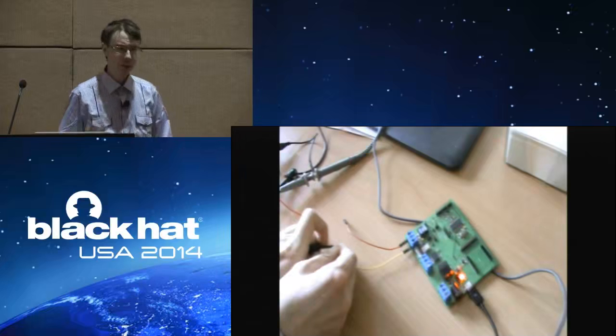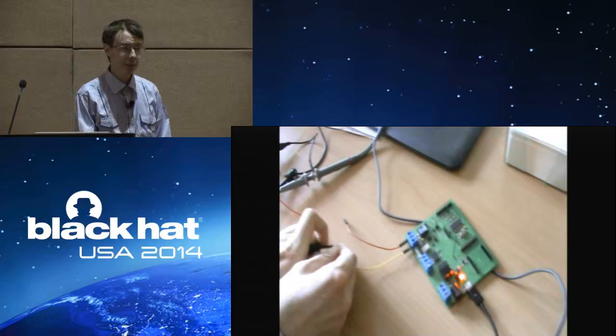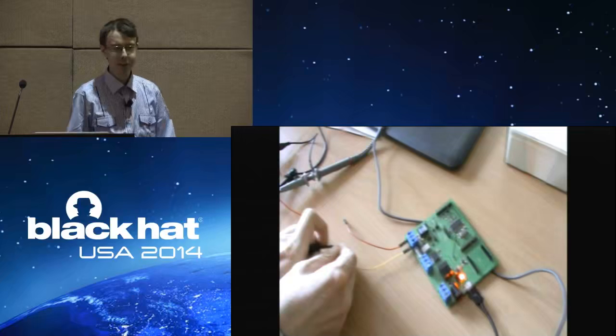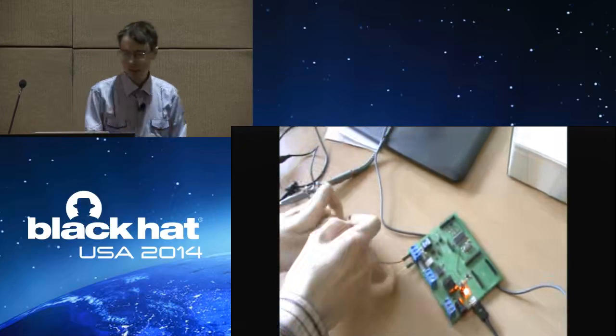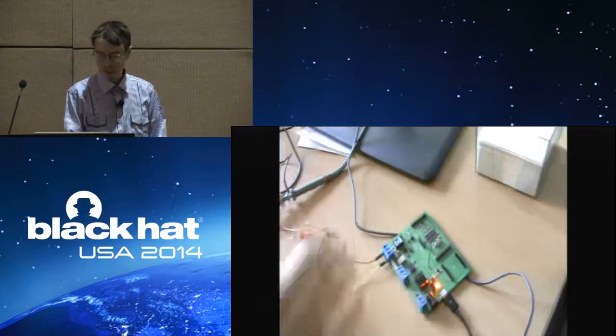The HART current loop is a pair of copper wires, and in reality to make the attack you don't need to intercept it or cut it off. You just need to connect the pair of wires in parallel. For example, you can use a pair of sewing needles soldered to copper wires. And now I just connect it with the lab connector.